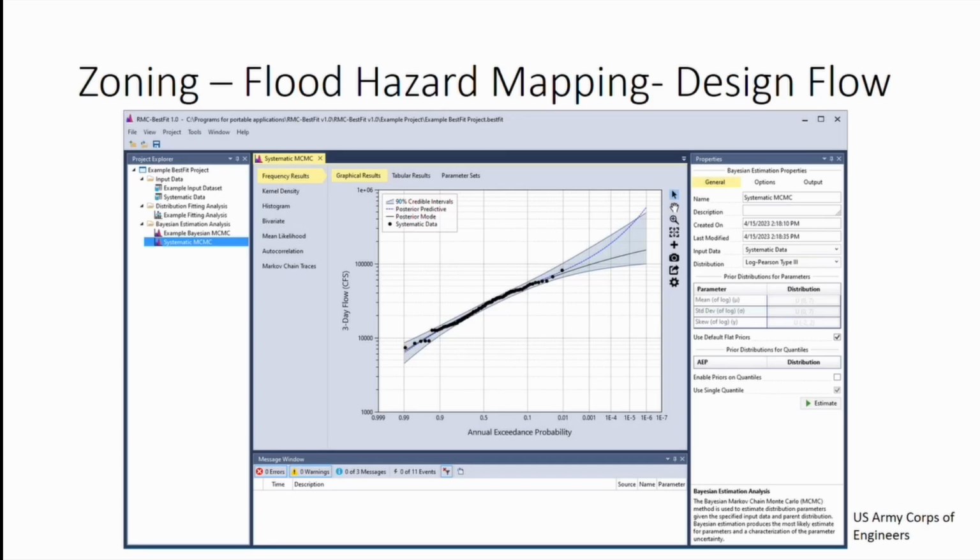Typically, we are looking at somewhere in the neighborhood of 30 years for the analysis to be statistically relevant. With that data set, we can fit a frequency distribution to the annual maximum series, then come up with our design events that ought to be routed through our hydraulic system.